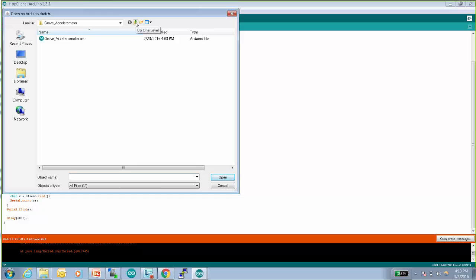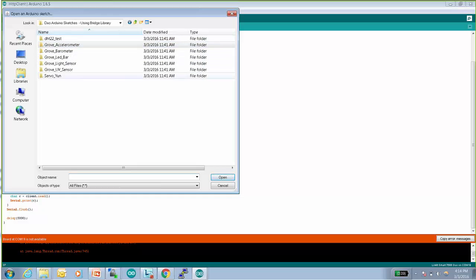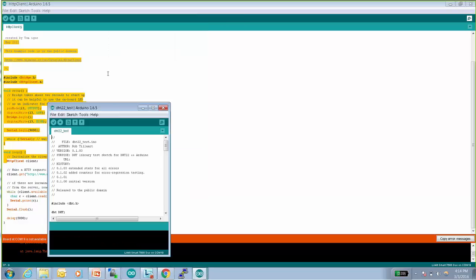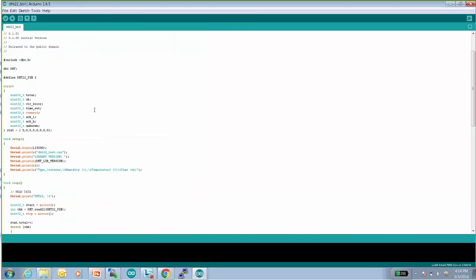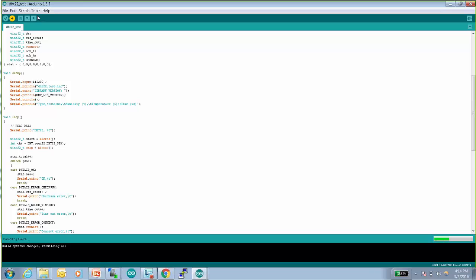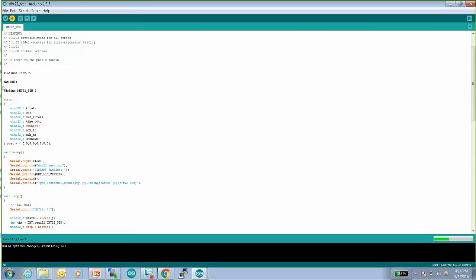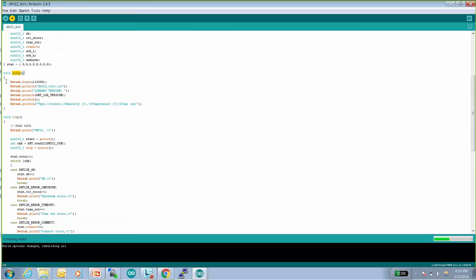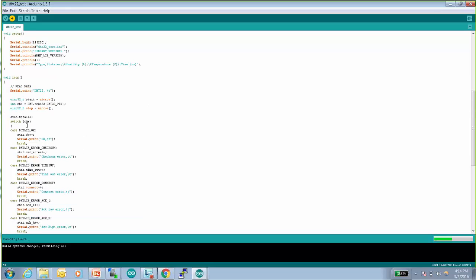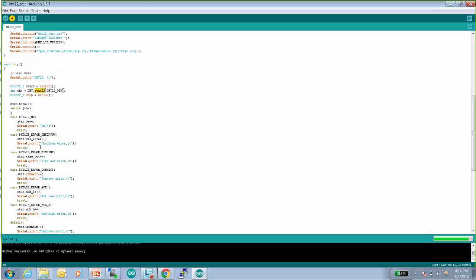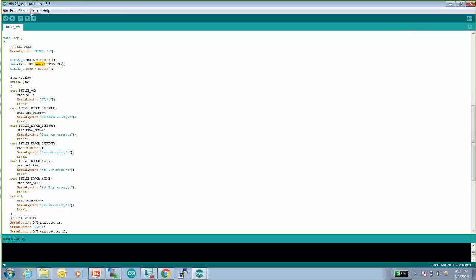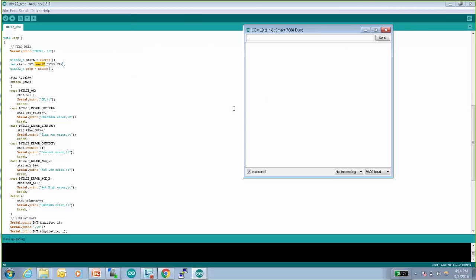And the other thing which I want to show is, say for example, a temperature sensor. This is another sensor I've connected with the board. I'm just uploading this to show the value from the temperature sensor. If you look at the example also, it's basically just printf statements, and it's using the DHT library to read the temperature. So the upload is done. Now let's see the values which are coming from this one.